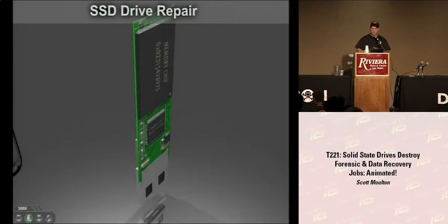The hard part was all this virtualization of some of the stuff that's custom that actually the control chip is doing. You don't know the layout of the content, so you don't know where these tables are and what's actually happening. It doesn't represent it like text, like something you would just find strings and you can do something with. So it's not the same and not as easy as it sounds. And if there's multiple chips, you don't know how that content is divided up either from that standpoint. So there are some more complicated things, but obviously it gets a lot harder when you're dealing with a solid-state disk, as you will see here in a second.